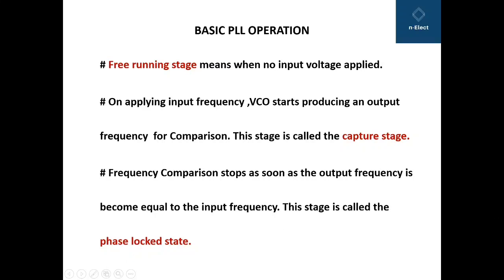I hope the idea of phase lock loop, its IC 565, the different versions of the IC, their differentiation through different parameters, the block diagram of phase lock loop and its basic working is clear to you from these slides.